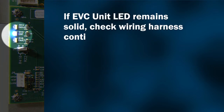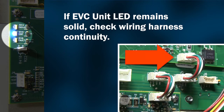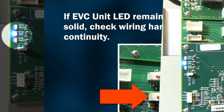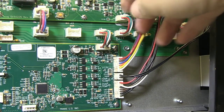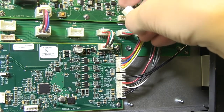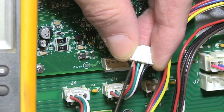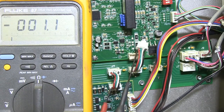If the EVC unit LED remains solid, we need to check continuity of the wiring harness from the AFC board through the distribution board to the EVC board. Detach the wiring harness at one end and check continuity of each lead, and repair or replace as necessary. If the unit LED is still solid, the EVC board is defective and must be replaced.